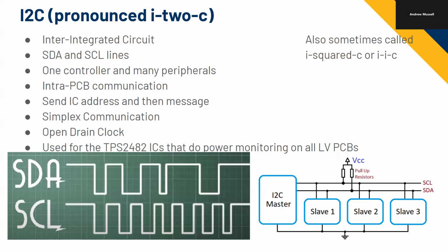I2C can actually have multiple controllers, but things get a bit more complicated, so I'm just telling you about the simplest case. If you want to create a bus with multiple controllers, you can read the I2C spec. Honestly, the I2C spec isn't very long. The TI application note is maybe 30 pages, and 5 pages of those are reference. It's less than an hour to read.